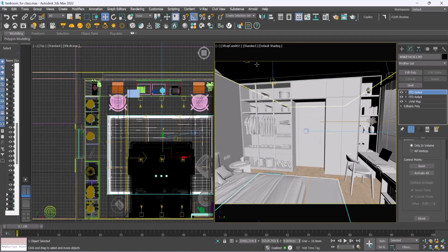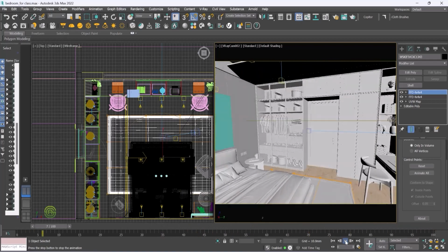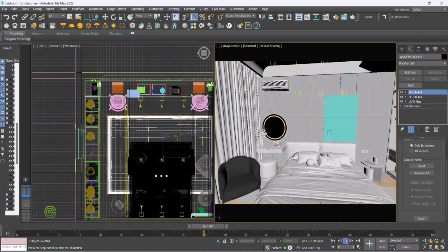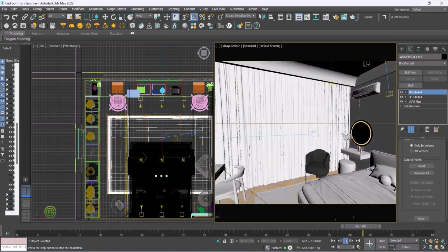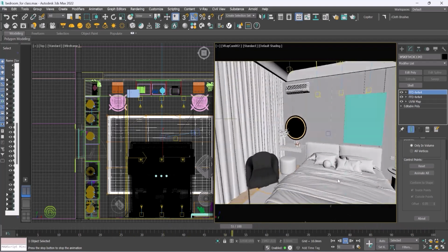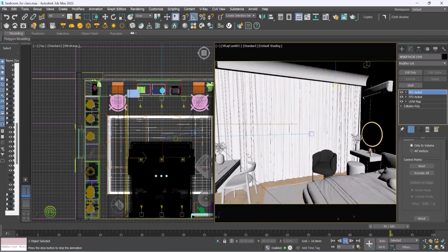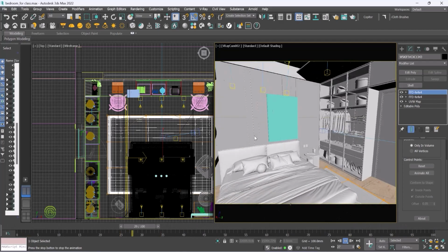So let's click on the viewport in the V-Ray Cam 02 and now just play this. So like this, we can create a walkthrough. So that's all, guys. Like this, using a camera with target and using the path, as we have created an arc as the path, by using both of these we can create a walkthrough like this. Now this walkthrough is moving very fast.